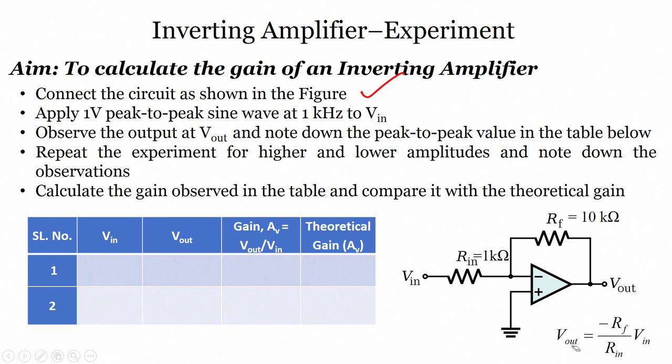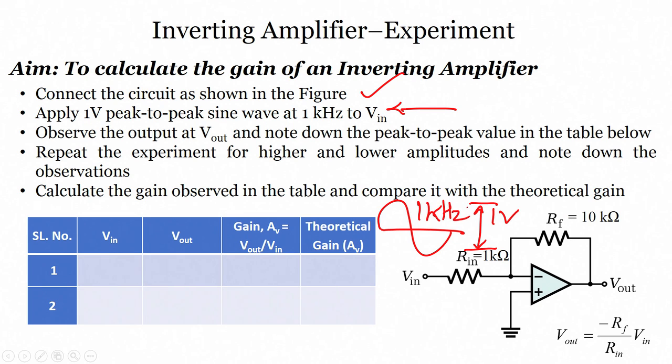Apply a sine wave, 1 volt peak to peak, with a frequency of 1 kilohertz.